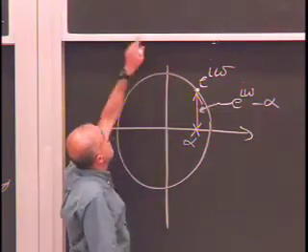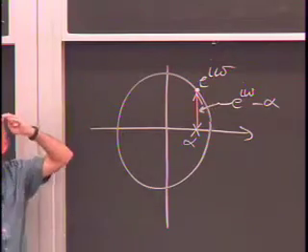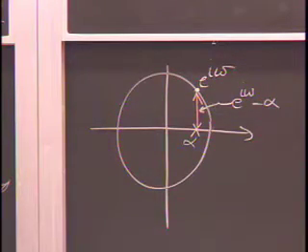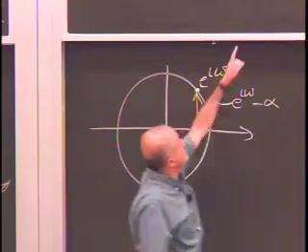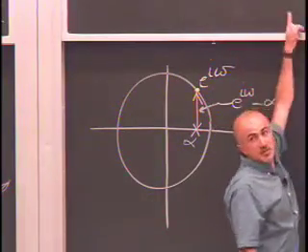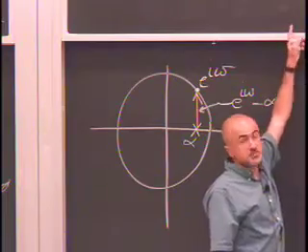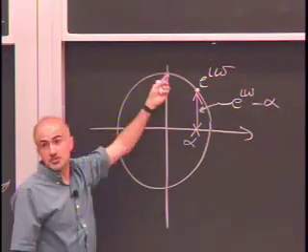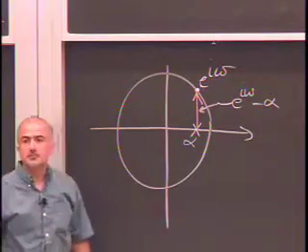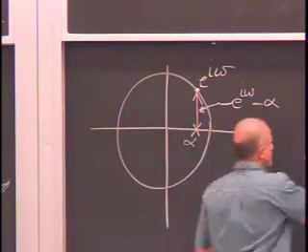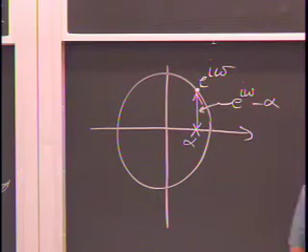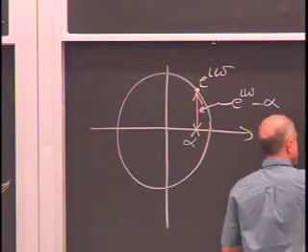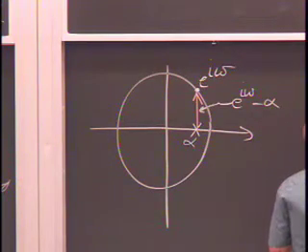So, when is the magnitude response at its peak value? When the red vector is what? Smallest. The red vector has the magnitude that's in the denominator. So when the denominator is the smallest, that's when the magnitude of H of omega is the largest. Where does that happen on the unit circle? At 0. So now I'm plotting. I'm going to plot from minus pi to pi. So at 0, I know I'm at peak.